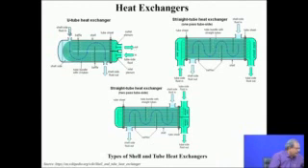You also have shell side fluid which is coming into the system, and then it is going to change its direction because of the presence of the baffles. Baffles are like a disc with one portion which is cut off.